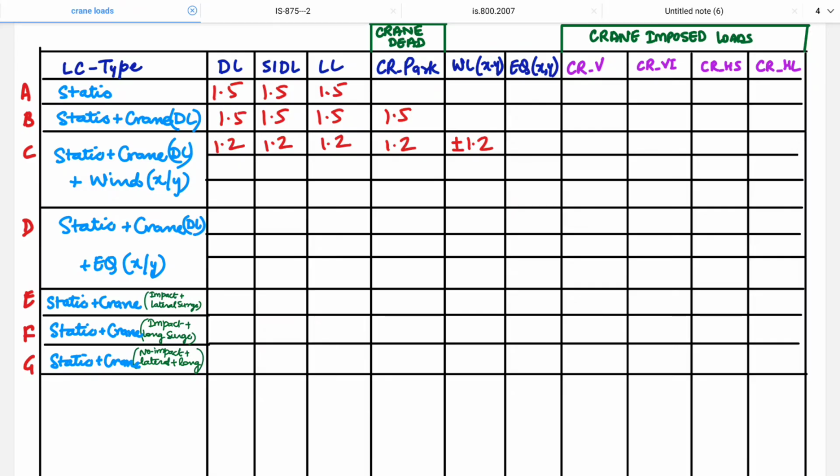For earthquake, if you do 100, 30, 30 as per IS 1893, and if you also include the Z directions, then for every load combination, this being called one set of load combinations, we will need 24 permutations of load combinations of 100, 30, 30. For more details, you can refer IS 1893. If you need more help on forming load combinations for 100, 30, 30 as per IS 1893, then please do comment. I will try to make a list.